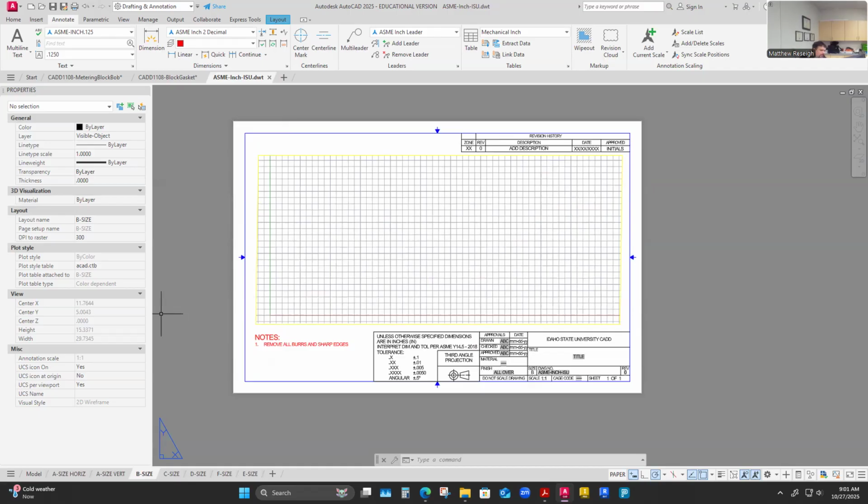So the stuff that's in the library is generally like parents, and then in a company you might build from those parent files and create children, which are new drawings, modified equipment from the parent. Some places will call that core equipment, like they've cored their equipment. It's in a core library. I can pull that out and work from it. My piece of equipment might be slightly modified from a core piece of equipment, but I can check out that core piece of equipment, make a copy of it, and then start to modify that copy. So configuration control is a library system for check in, check out, make copies. And so we're not always starting from total scratch.